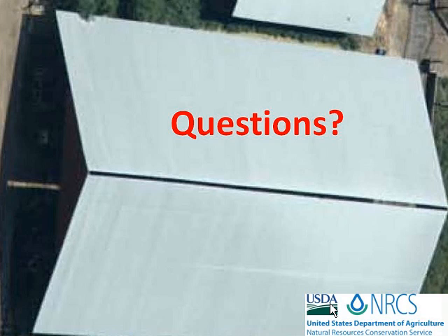And likely, that's average. So you're looking at sizing for an average year. You may want to add some safety factor to try to cover drought years. If you want to be really sure that you're covering drought years, then you're going to have to go to a simulation like a SPA model, or we used to have a computer software program called ResOp that unfortunately is DOS-based, so I think we've lost that, but you could use that. It was a monthly time step type of reservoir sizing software.